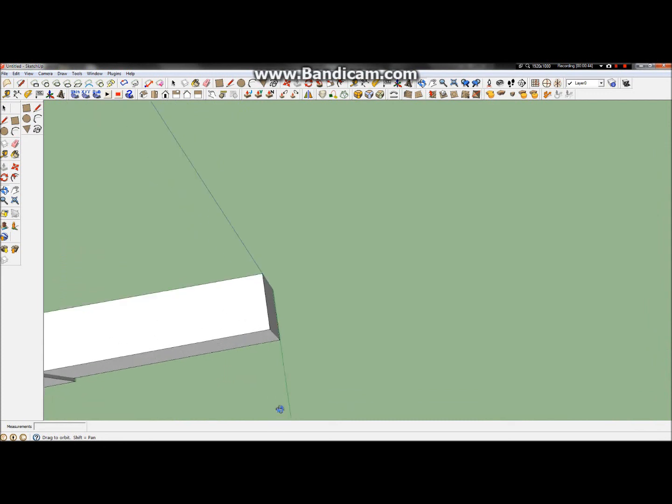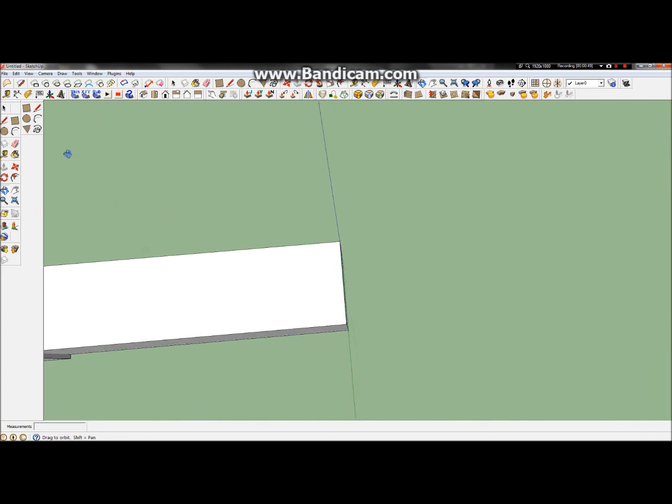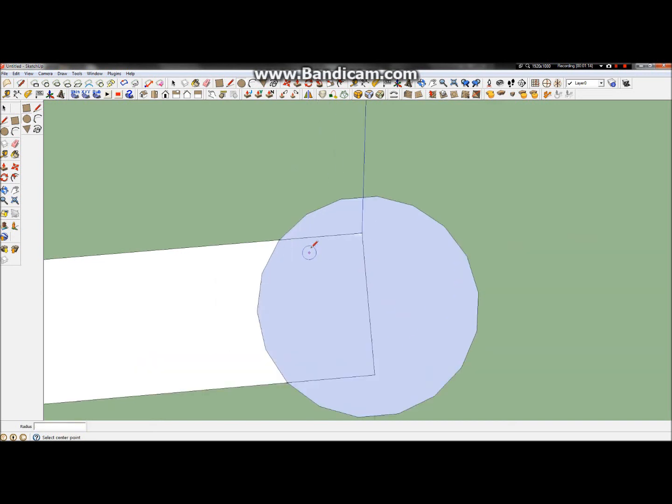And we'll go ahead and draw this out. So first of all, we're just going to start out with a cylinder. And that should be set. Let's make sure it's set to 18 sides. Alright, so what we said the diameter was 2.8, so we're going to want that to be 1.4 on the radius. There you go.